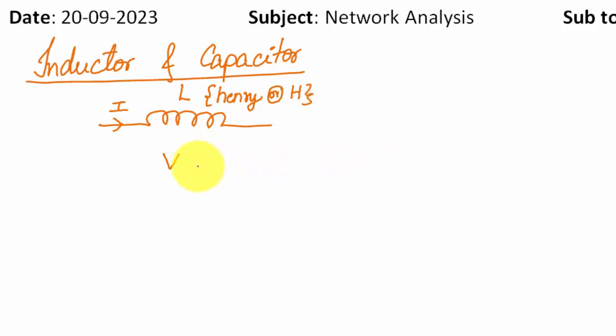Okay. Now what is the voltage drop across the inductor? You see, the voltage drop we will be taking as V equals I times jωL, or let us not talk about j over here, let us talk about I times XL, where XL is ωL.